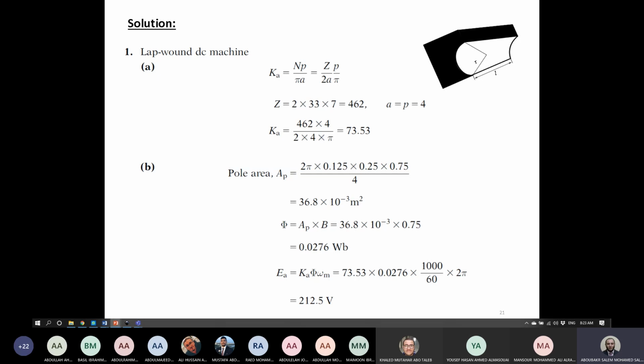Okay? If we consider a machine, guys, a machine cannot work with an odd number of poles. How does it work? All the time the flux is moving from N to S. So in order to have flux pass, you have to have 2 poles, N and S. So if you have a third pole, how is the flux going to move?